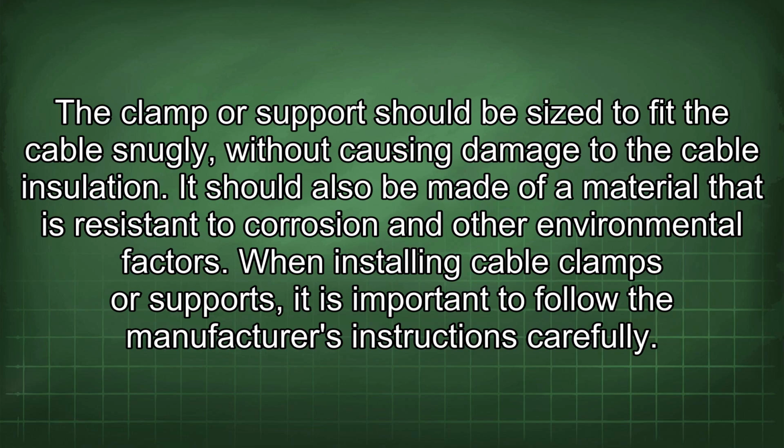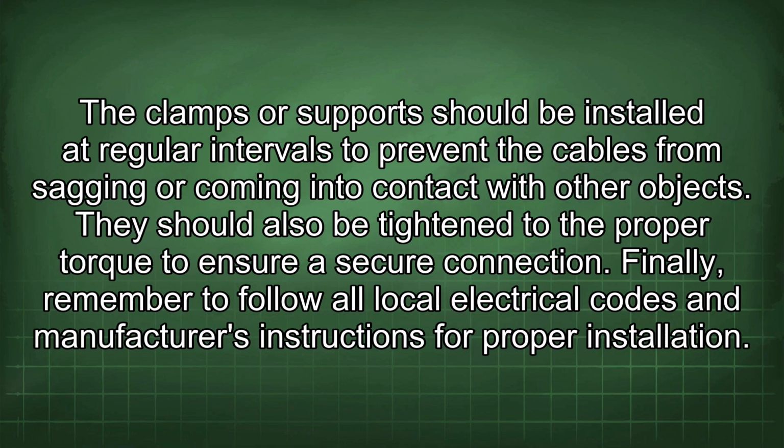When installing cable clamps or supports, it is important to follow the manufacturer's instructions carefully. The clamps or supports should be installed at regular intervals to prevent the cables from sagging or coming into contact with other objects. They should also be tightened to the proper torque to ensure a secure connection.